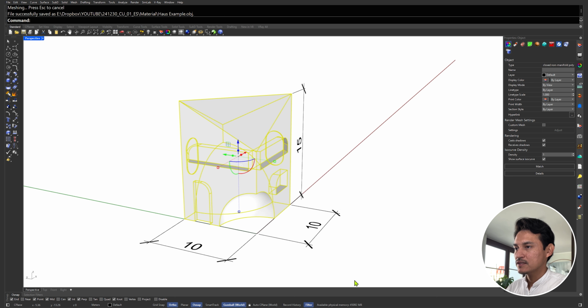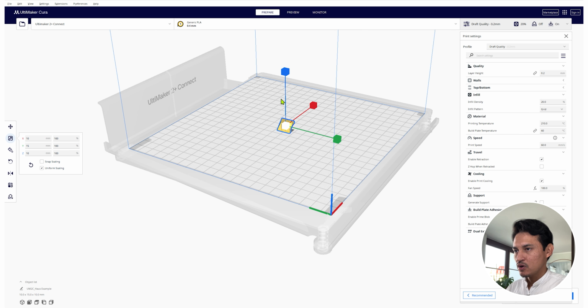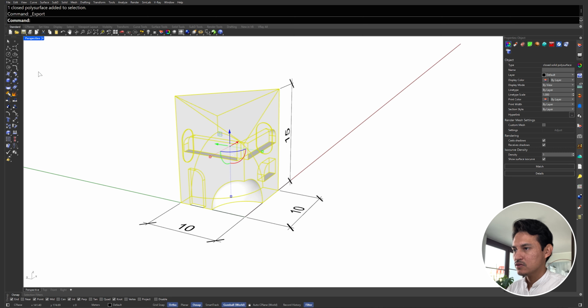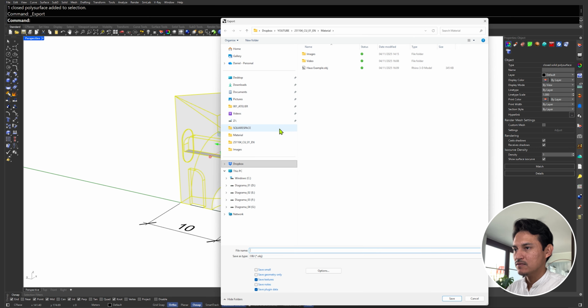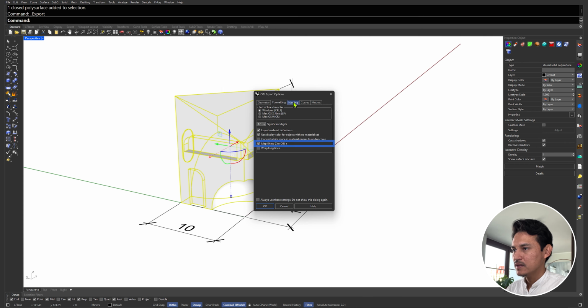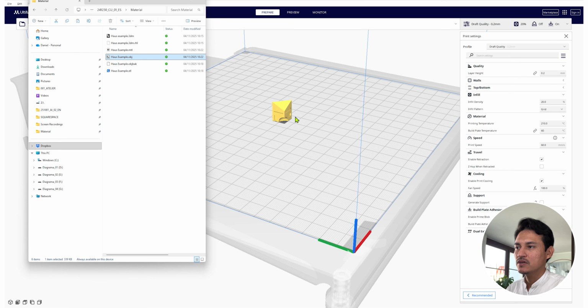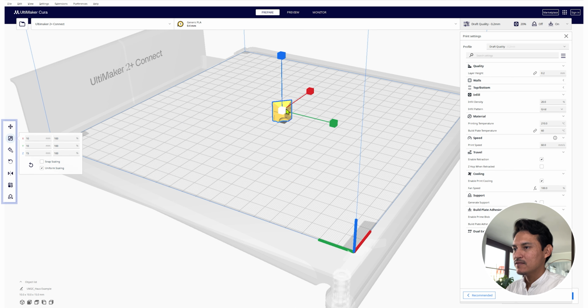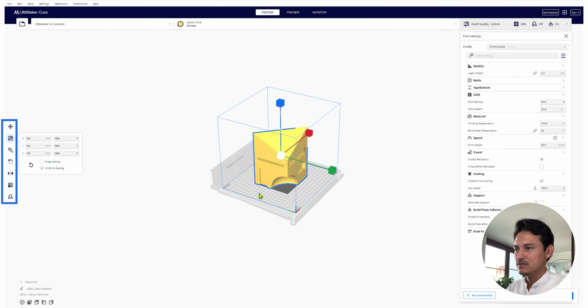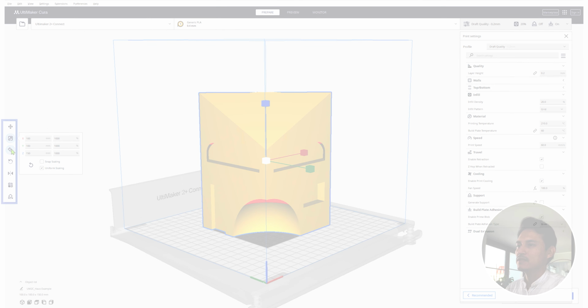If you export it as OBJ and the geometries appear rotated 90 degrees, that's not a problem. To correct this orientation, you have to export again and uncheck in formatting the Map Rhino Z to OBJ Y and the import will work. If you are exporting as STL or 3ds, you won't have this issue. Now, on the vertical left tab, you can see the basic operations like moving, scaling, rotating, mirroring that you can use to manipulate your imported geometries.